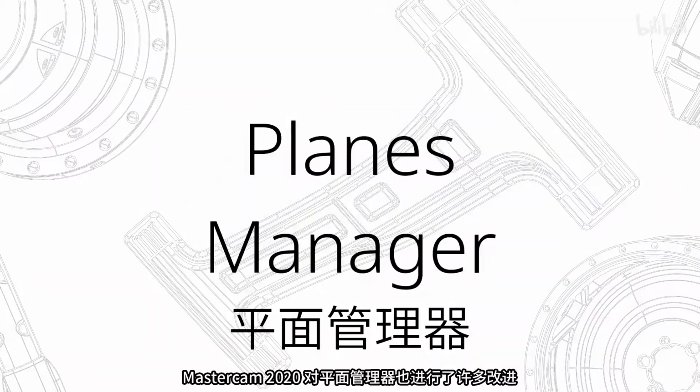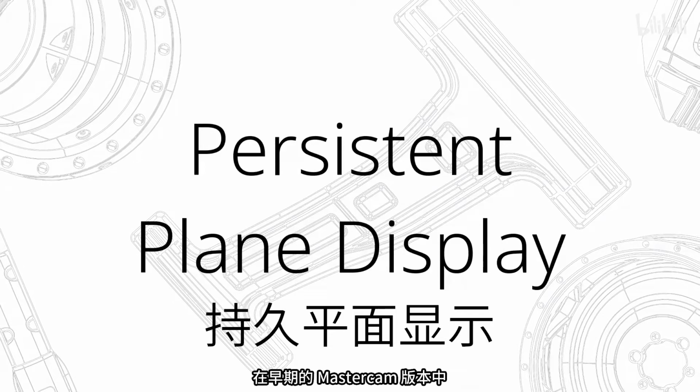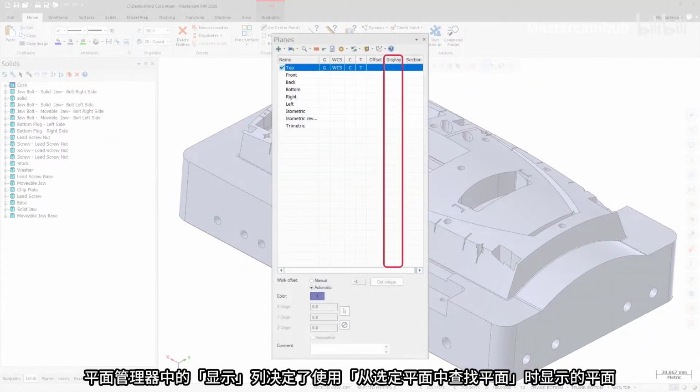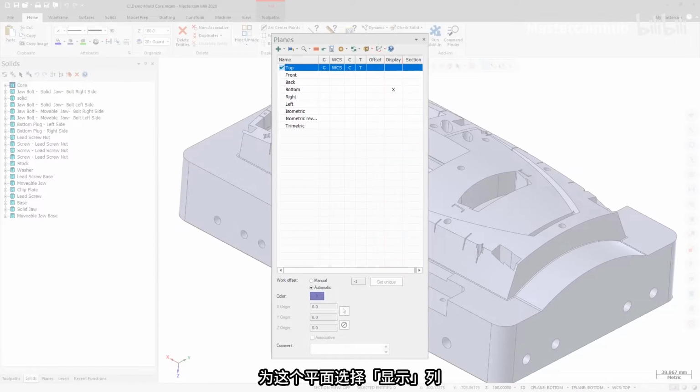There have also been numerous enhancements to the Planes Manager as well. In previous Mastercam versions, the display column in the Planes Manager determined which planes display when using Find a Plane from Plane. In Mastercam 2020, this column controls which plane nomens display in the graphics area when the Show Nomens button is toggled on. If you select the display column for a plane, an X will appear in the column.